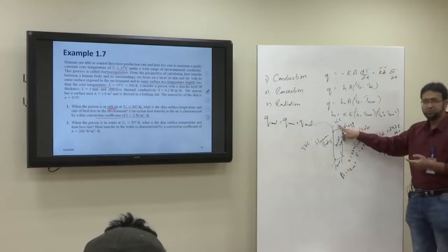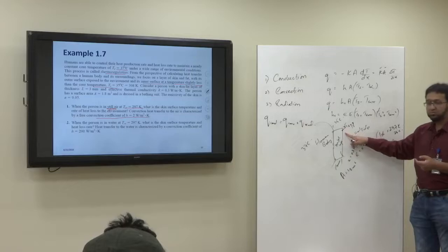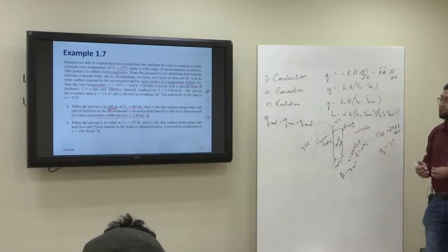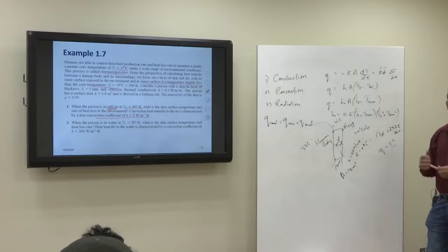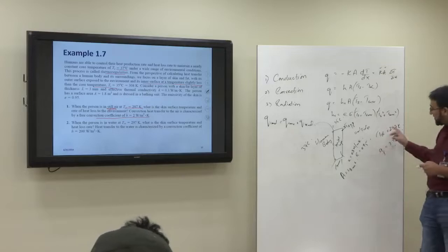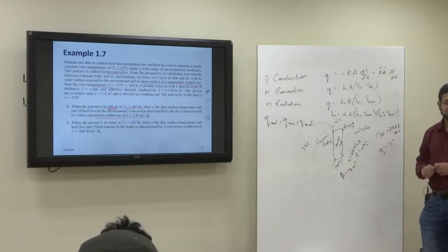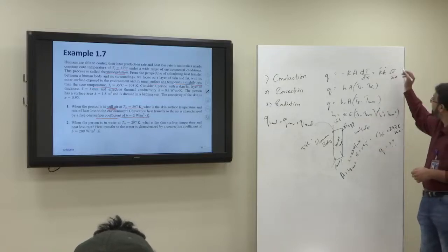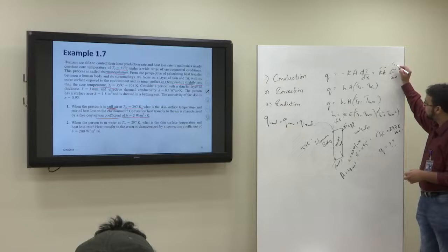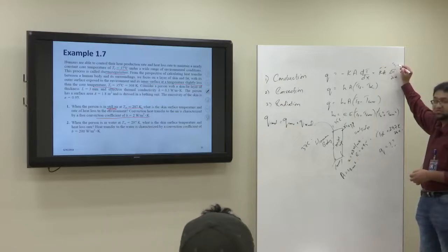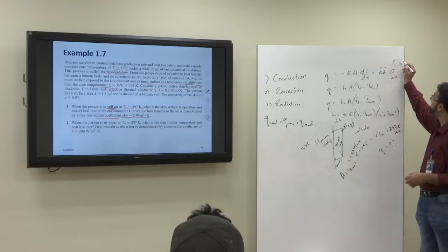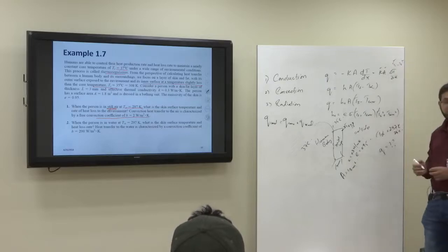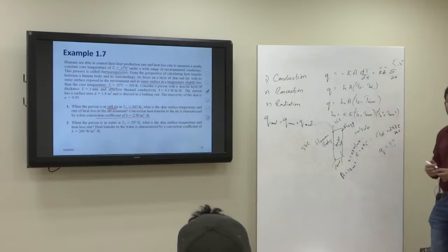Inner temperature you know, 35. Outer do you know? We can take from the still air. It is Ts, surface of the unknown. This we don't know. T infinity is the outside air temperature and they are not the same. Very clear? So this delta T will be T inner minus Ts. T inner is known but Ts is unknown. Okay? What about delta X? Huh? Known. This is known.